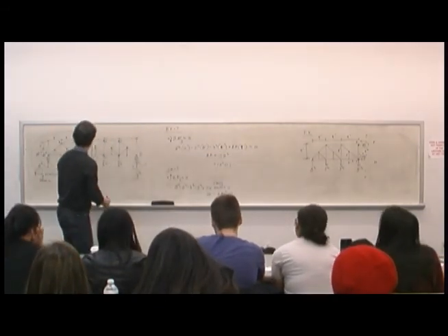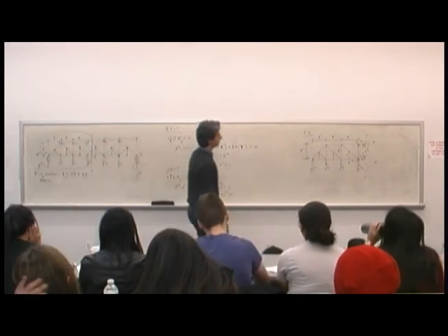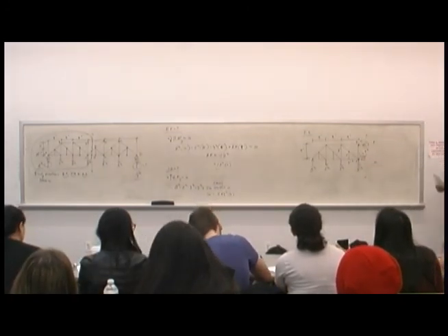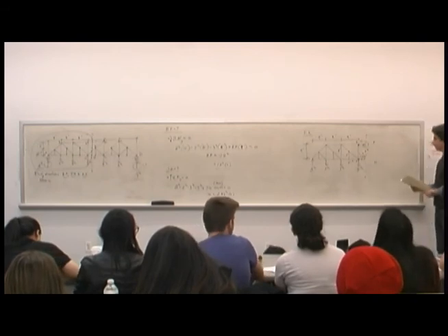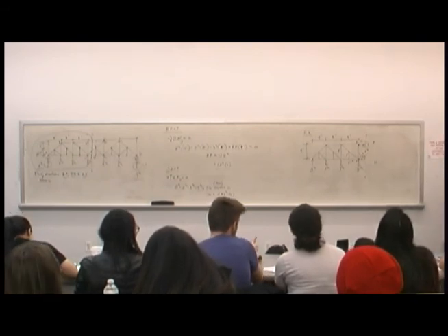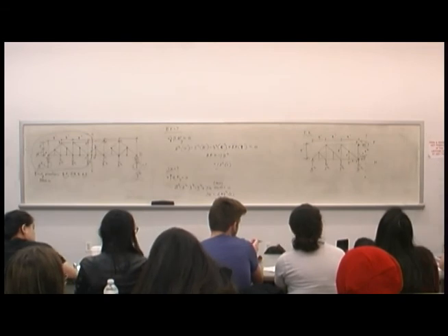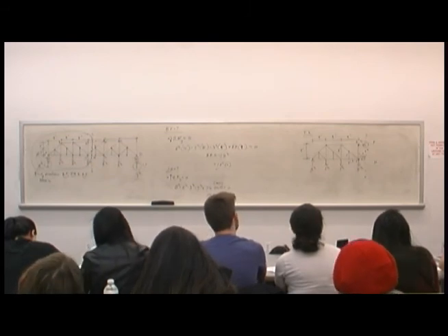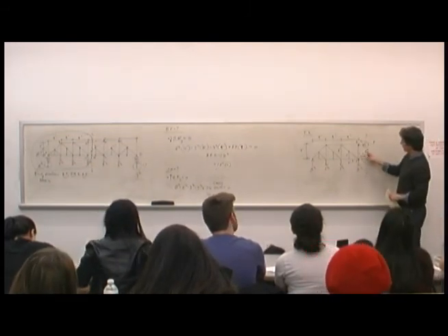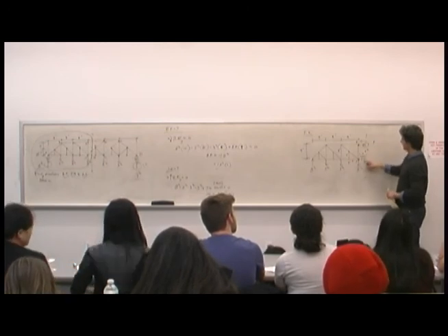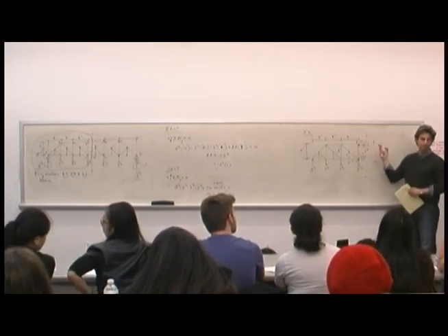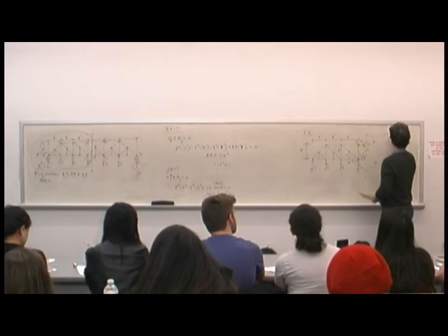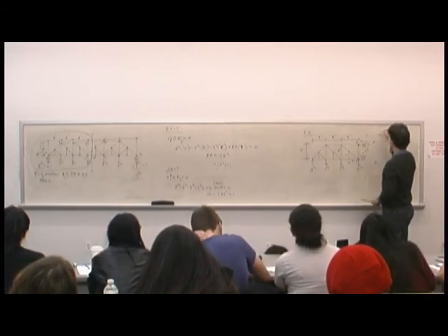And then the last one we're looking for is HJ, which is this horizontal one. JH here. So how do I do that? Is it 0? Why do you think it's 0? Well, you have the component of JK, you have JH, and then you have EF, right? So we want to balance that. So let's do the sum of the forces in the x direction. We're looking for JH.